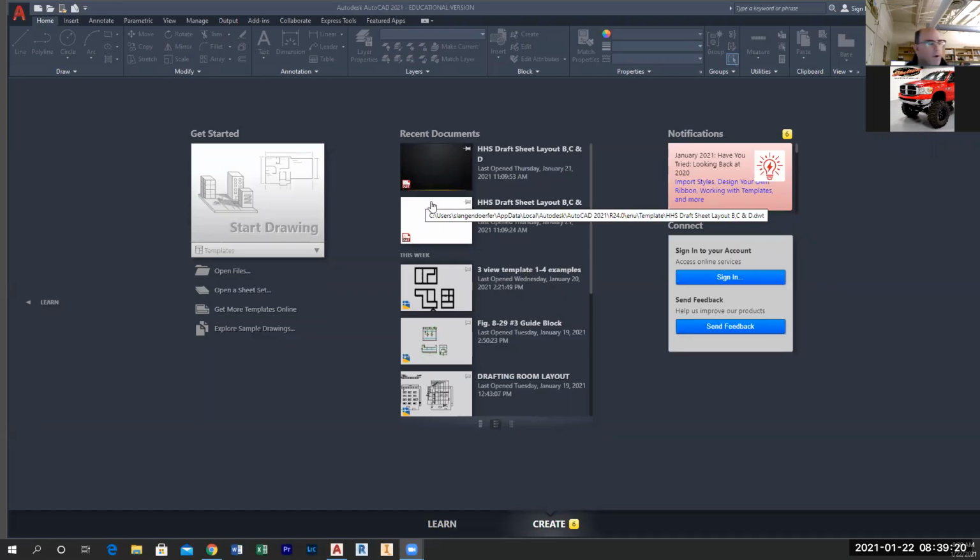All right, so what am I doing? I'm recording right now, but what I'm going to do is 3-view drawings. Up until this point, we did single view drawings. We did a couple of sketches out of the book on graph paper of 3-view drawings. And what you want to do is a front view, right side view, and top view. You want to make sure that you put hidden lines in where they need to go, okay? So we did that sketching wise.